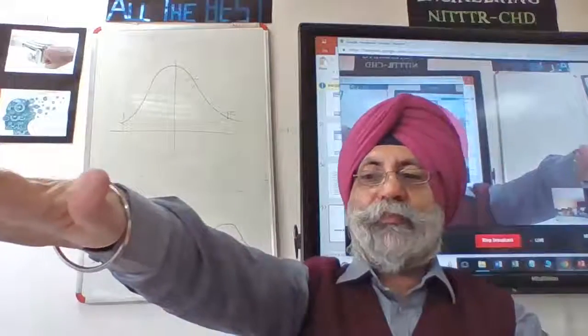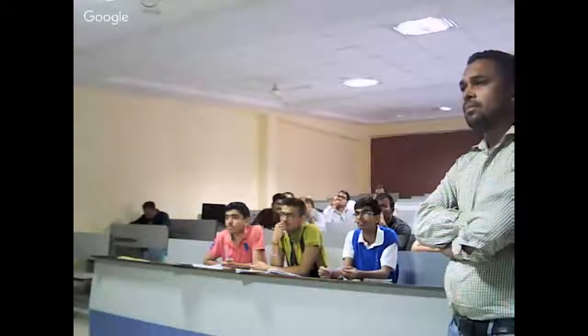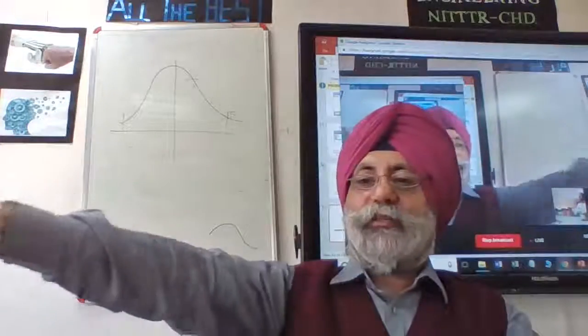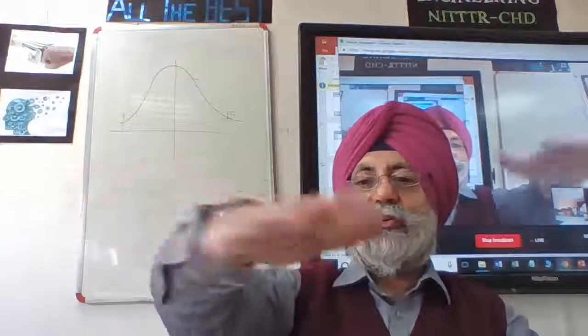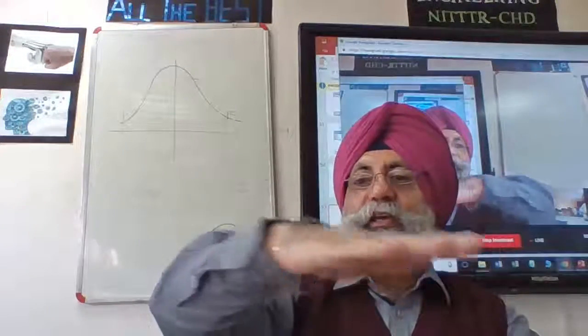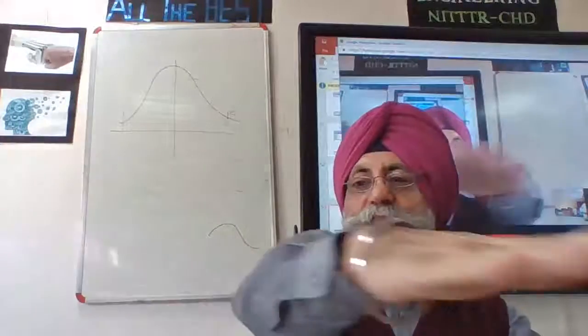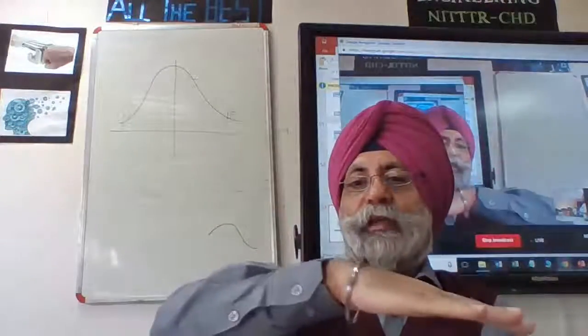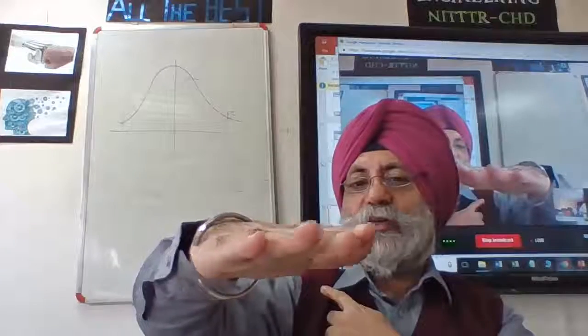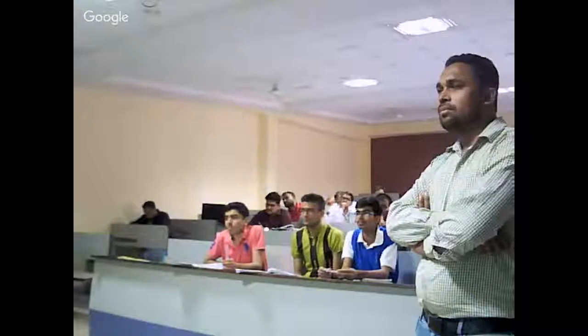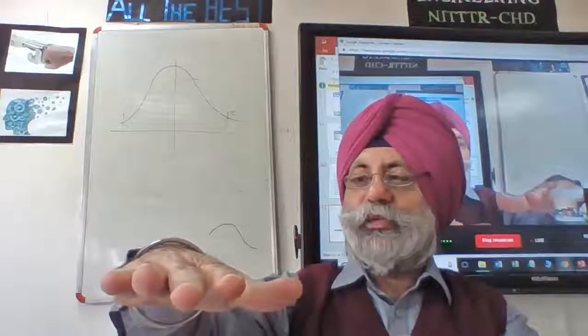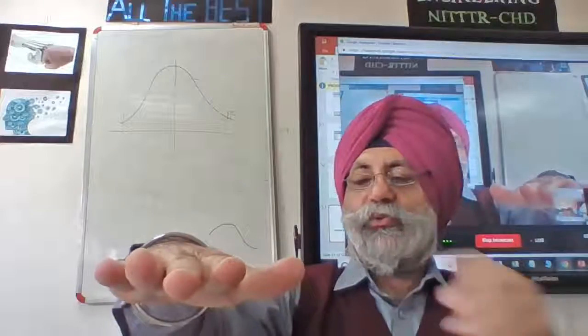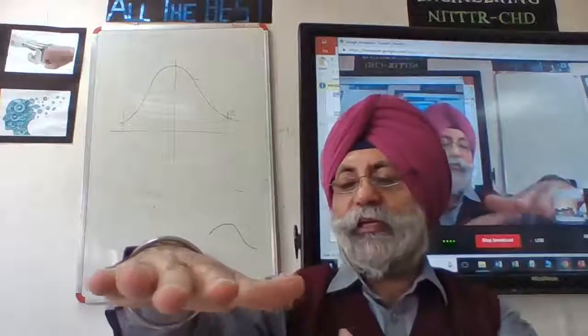However, if you can imagine that if you bend your arm, the SCARA arm can move in the horizontal plane at the shoulder joint or at the elbow joint. It cannot move up and down. So the arm can move only in one plane, but it has two movements, at the shoulder and at the elbow. So you can say that arm movement is only in a lamina, only in one plane.